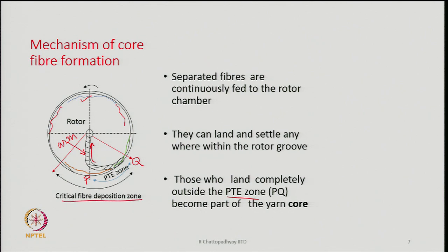If I say PQ is the PTE zone, then on the other side also there is a little, we can extend it on the left-hand side also, and if I give a name to this particular point, let us say R, then from Q to R is an area within the rotor groove which is known as the critical fiber deposition zone. That is, if the fibers lie within this zone, then there is some possibility that the fiber will be part of the sheath fibers.